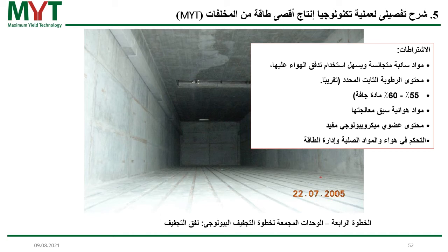You need a loose and homogeneous and air-flowing friendly material which you can put into the tunnels, because biological drying means that you put the waste into the tunnel and then you blow air from underneath through the waste until the ceiling. So you provide a lot of air into the waste, and this is how the microorganisms which are inside the waste receive the oxygen. And with the oxygen, they produce heating energy. They feed on the organic compounds, they produce heating energy, and this is the energy we use for the drying process. So it's completely biological.